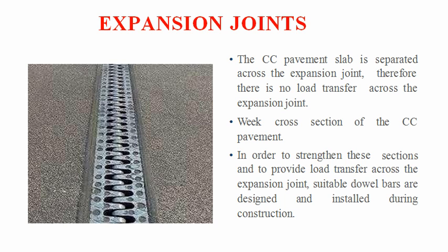The dowels would develop high bending and bearing stress with wider openings, so it is recommended not to have a gap of more than 25 centimeter in any case. The Indian Road Congress has recommended that the maximum spacing between the expansion joints should not exceed 140 meter for the rough interface layers.